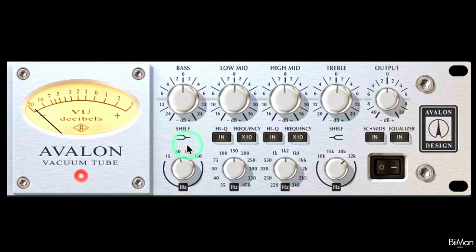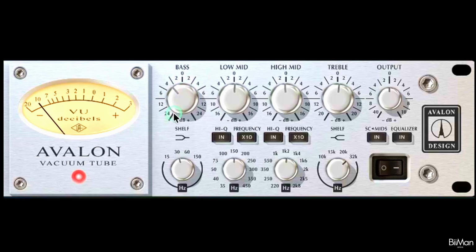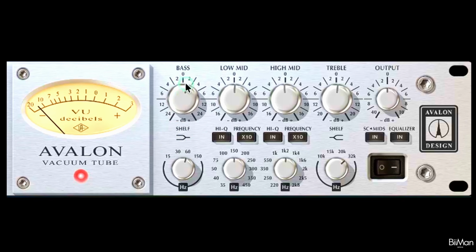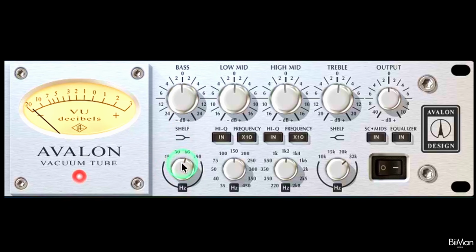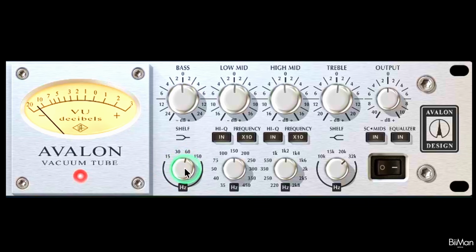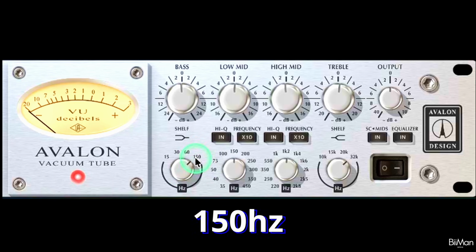The different EQ controls are: first, you have the bass gain, which lets you boost and attenuate the bass frequency with a shelving filter up to +24 dB and -24 dB respectively. Right below that, you have the bass frequency knob to select the different bass frequencies from. This goes from 15 Hz to 150 Hz.